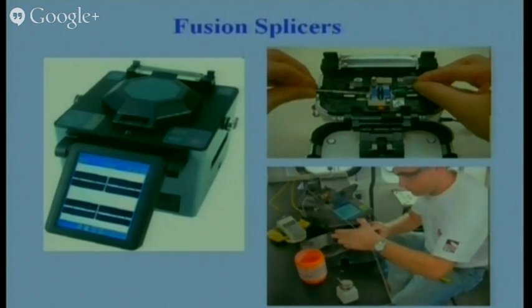Initially you will find different switches on this. Once you position the fiber, you have to press the set button. So it will check for the alignment and cuts. After set is passed, you have to press the arc. So it is a two-stage process. Once the arc is there, it will take some time. So all this processing is required.